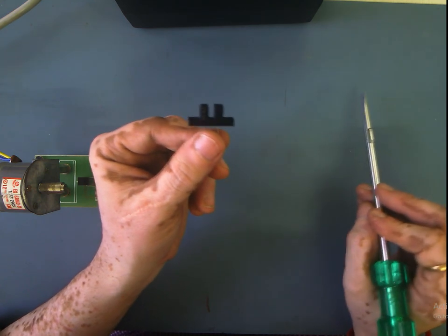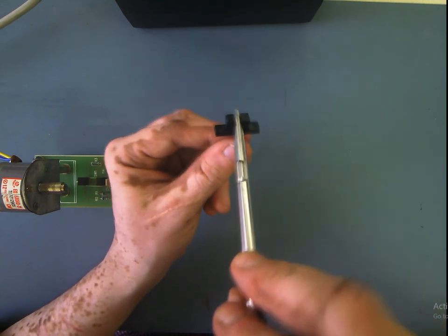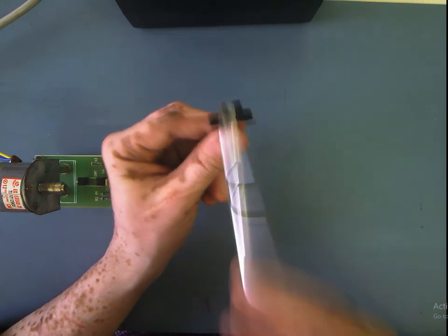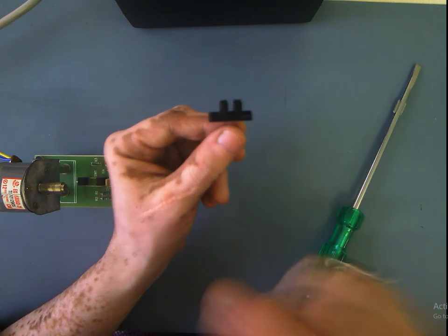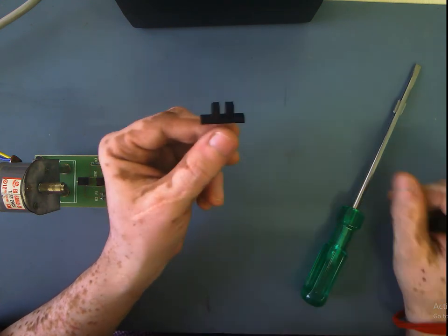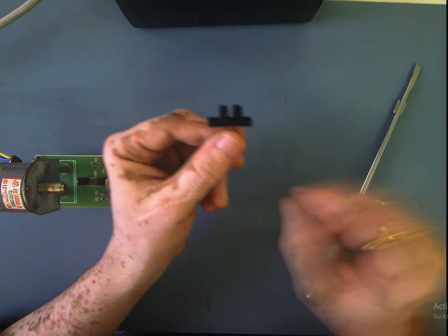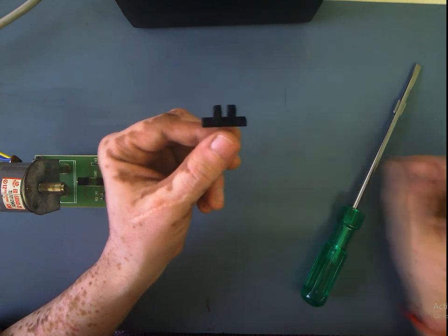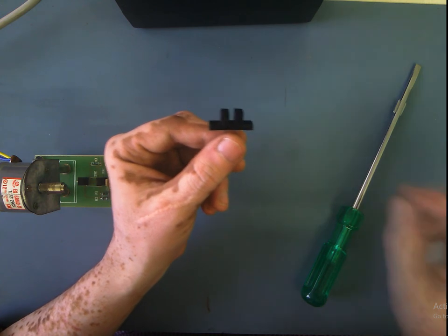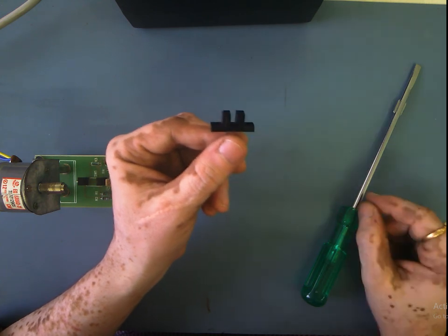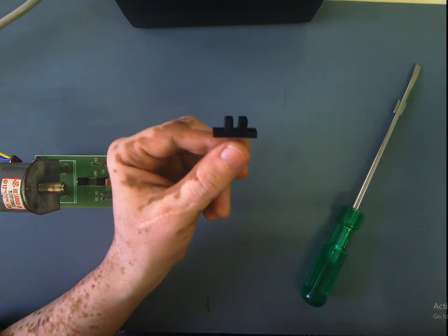Now if I put an obstacle in between, suppose I have put this obstacle, then no IR signal will be able to reach the phototransistor. So now what will happen? The transistor will no more be in the conducting state, and when the transistor is not conducting, the entire supply voltage will be reflected across the collector emitter terminal. So this is the basic principle of operation.